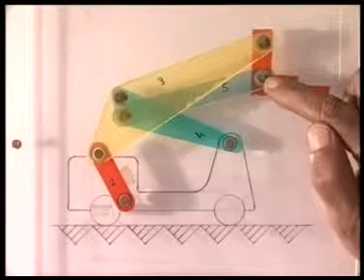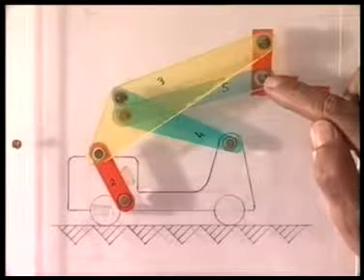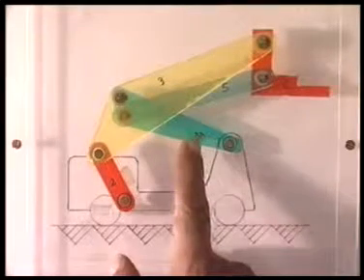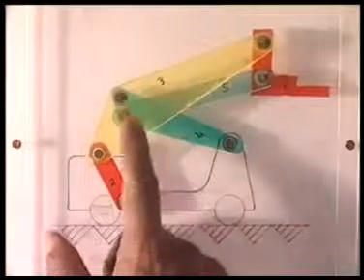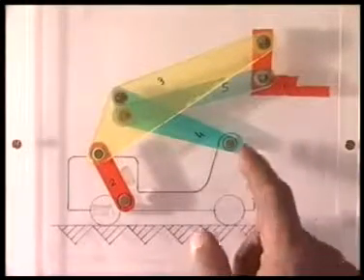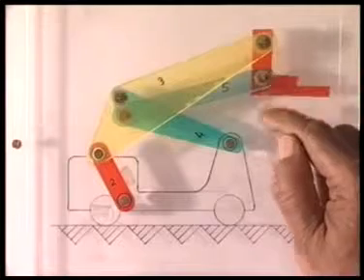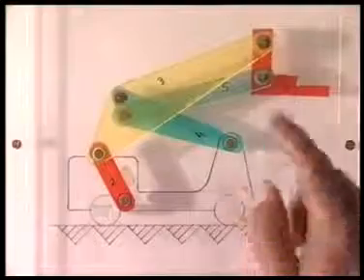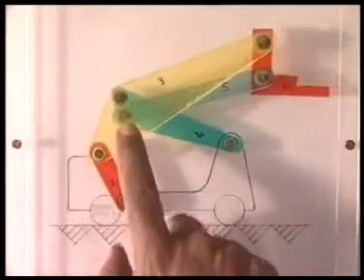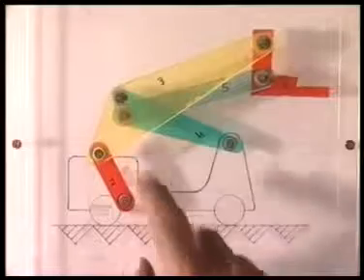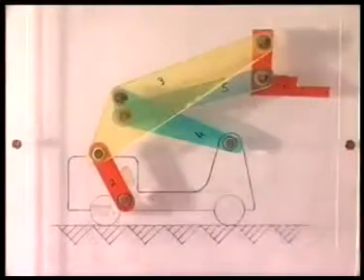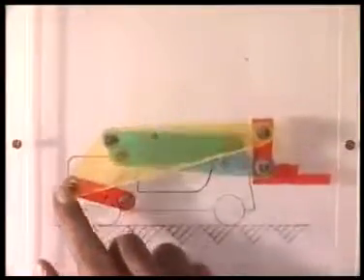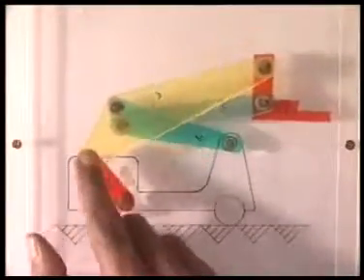After choosing this point D, we found the inverted positions of the D corresponding to the second and third configuration, holding this link, that is link number 4, fixed at its first configuration. And the center of the circle passing through these three inverted positions of D, namely D11, D21 and D31, I found the center of that circle at this point, which I called E. Finally, we get this 6-link mechanism where I have a forklifter without any vertical guide.